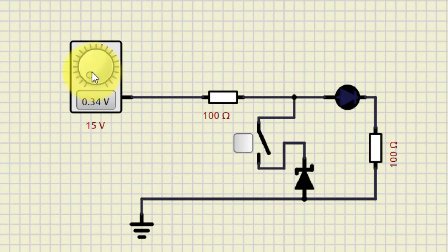Now when we turn it on and increase the voltage, this LED glows. This is yellow, it is glowing. Now if we further increase the voltage, this red mark in this simulation shows that the LED has been damaged. It receives more voltage and more current flows through it, and it destroys the LED. This power supply, if it is an unregulated power supply, can supply any voltage, so it can damage other circuits, thus it has damaged the LED.